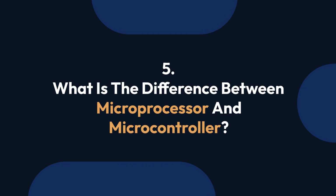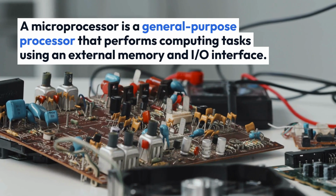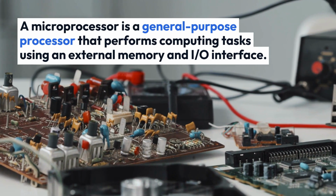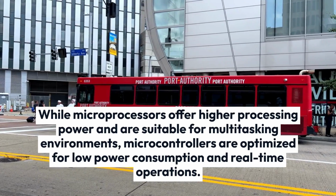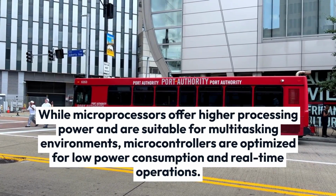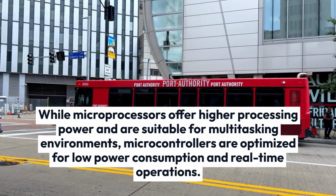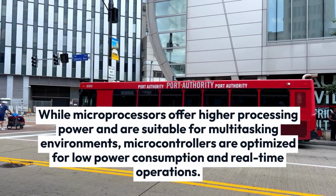5. What is the difference between microprocessor and microcontroller? A microprocessor is a general-purpose processor that performs computing tasks using an external memory and I/O interface. It is commonly used in PCs and laptops. A microcontroller, on the other hand, is a compact integrated circuit that includes a processor core, memory, and input-output peripherals all on one chip.